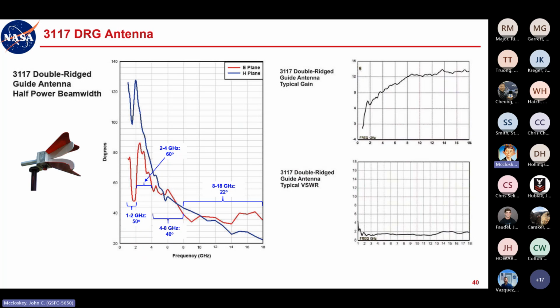So if we want to include more antenna positions to get better coverage in this higher frequency range, we can do that, but we don't have to do that in the lower frequency ranges where we've got bigger spot sizes. There's no particular reason to increase the number of antenna positions, which is going to increase the amount of scan time, where we've got these nice big spot sizes down here.